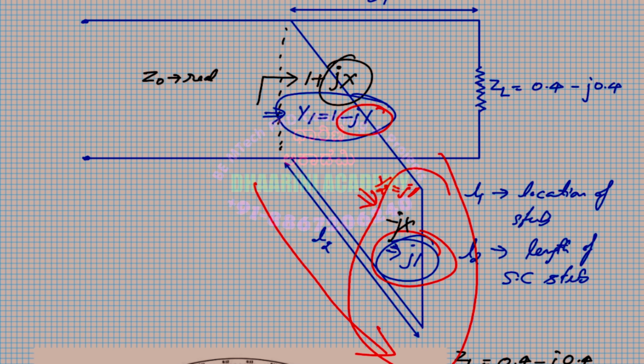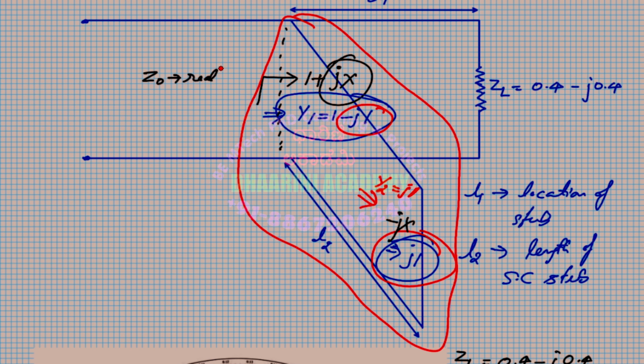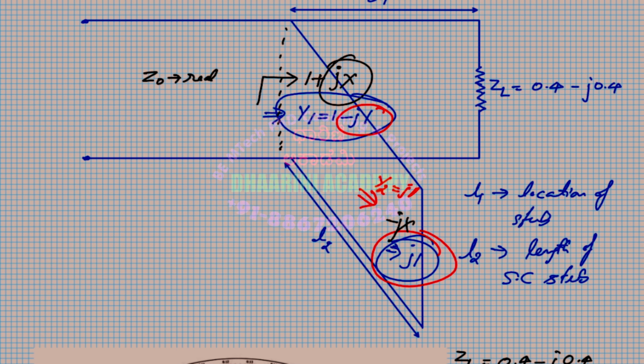This is the short circuit what I see here, right? Is it a load or is it a generator? Are you sure? Consider only this part. This is my transmission line. Don't consider the original transmission line, that is not there now. So the short circuit is a load, right? That means this is the generator now. For this stub which we are adding now, this part will look like a generator, and the short circuit there is the load.